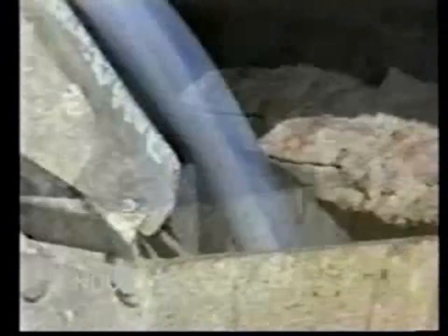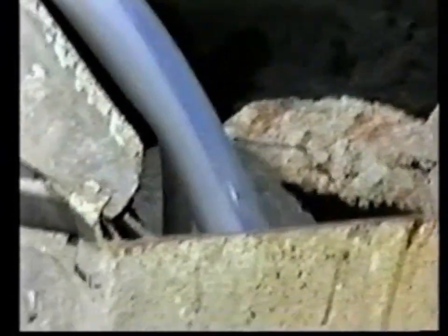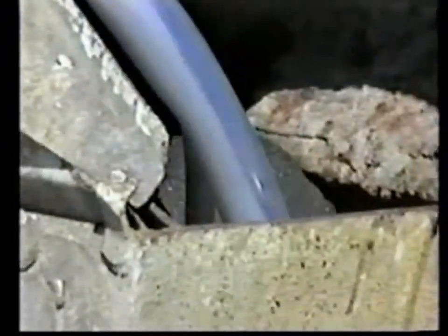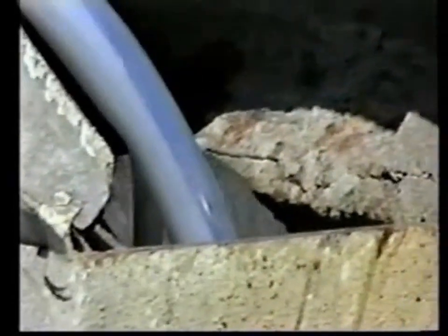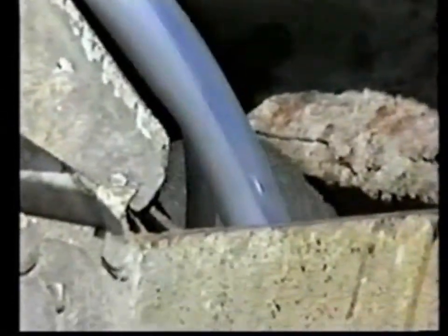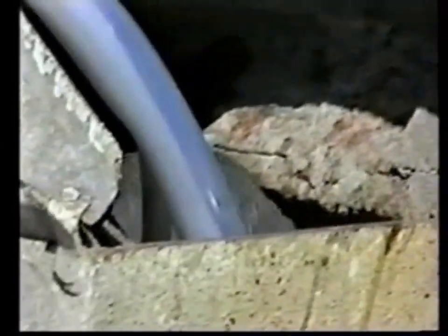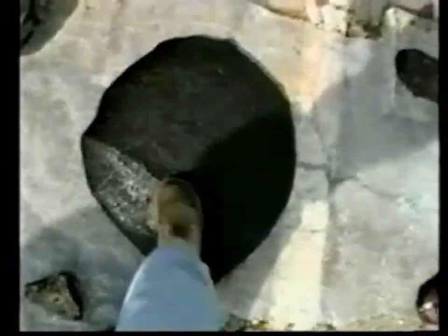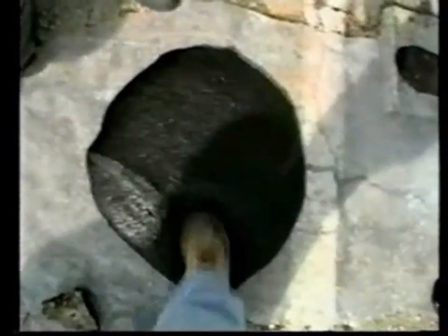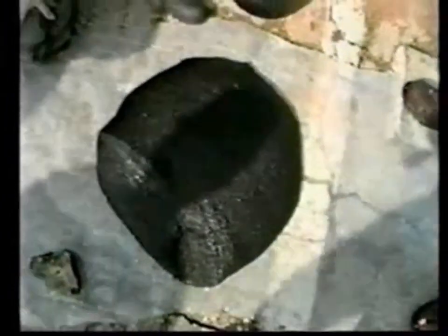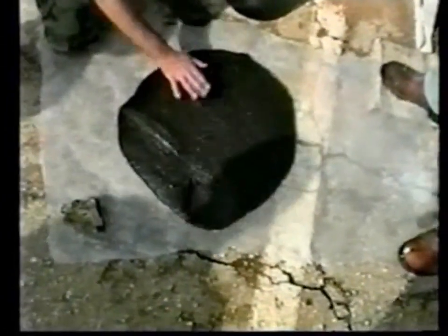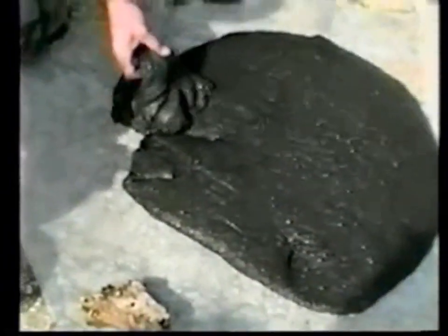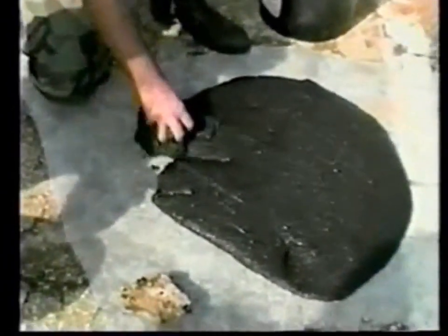The rate of travel for the conveyor belt and the pumping of liquids controls the consistency of the iron mix. This varied slightly during the demonstration, yielding different densities of the slurry to be injected. The result is a very viscous mixture. Densities up to 190 pounds per cubic foot were obtainable with this mix. This is compared to the dry bulk density of iron, which is 217 pounds per cubic foot.